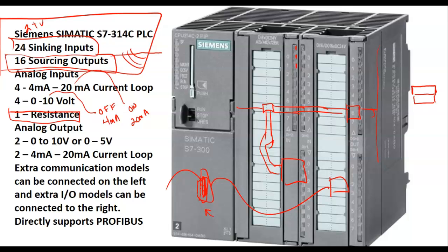If you go out there and somebody triggers the sensor and the light doesn't change, then either the sensor's bad or you got a bad wire coming from the sensor. When an output goes true, its LED is going to come on. So an output has an LED too, so you'll have to identify those. If you tell it to generate an output, then that LED would come on. That would tell you that it switched 24 volts to the output. And then the relay doesn't come in. Well, on that, you might have to pull out a meter, right? You understand, and verify that the 24 volts is getting there.